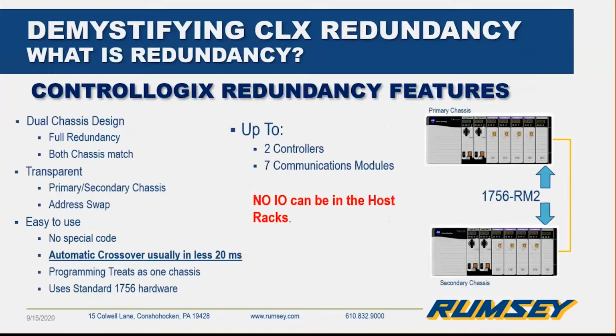In short, today, the latest version is version 32. It supports 2 controllers and 7 communication modules. So that does mean you could have 7 Ethernet modules in the primary and secondary rack. No I/O goes in these racks. Keep that in mind. It's always remotely controlled I/O.